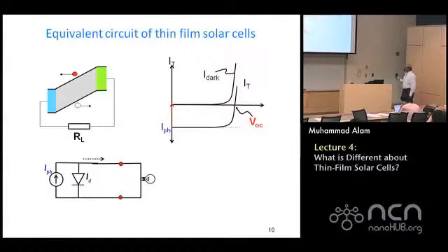And so the voltage at which there is no current is called the open circuit voltage, and the point where you want to operate is the maximum power point. How do you find that point? Well, if you remember from your circuit days, if you have one element that has this particular IV characteristic, and you have a load line, then wherever that intersects, that red point, is where the power would be. Now, what is the maximum power? Maximum power would be whatever corresponds to the red point, with a voltage that is a little less than VOC, and a current which is a little less than the ideal photocurrent, the short circuit current.